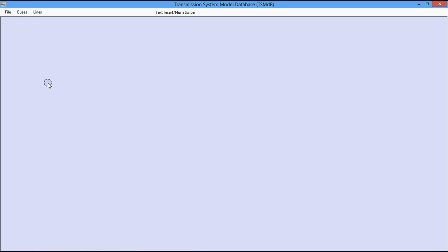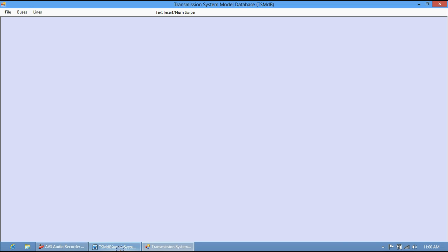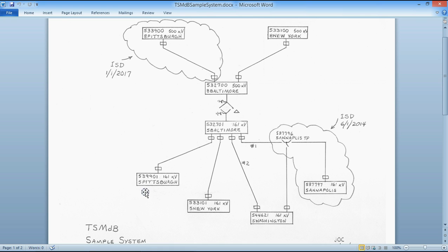Now, at the start of the video, I said I was going to make some changes to the database so that you could see how to do this. In the interest of time, let's only do one of these, and let's do the one that's a little more complicated. Let's break the Baltimore, Washington #1 line, add Annapolis tap, and then put in the Annapolis 161 kV tap line.